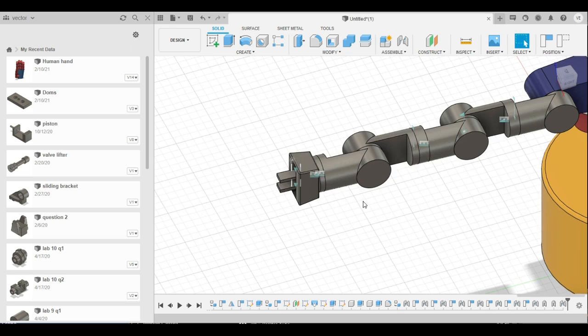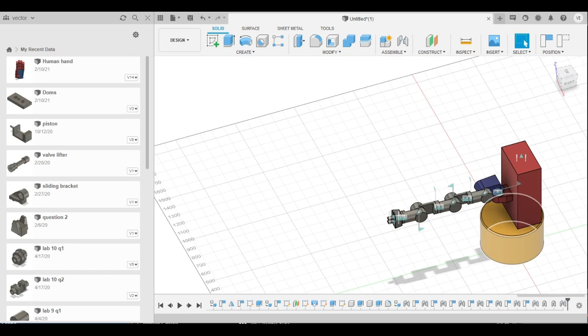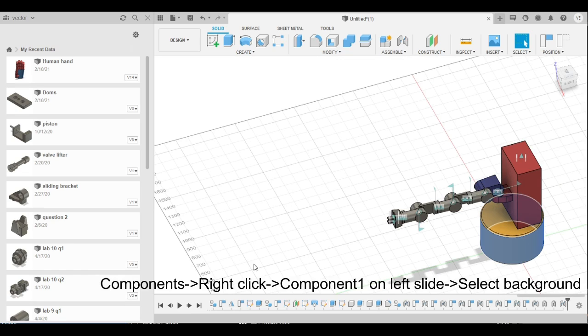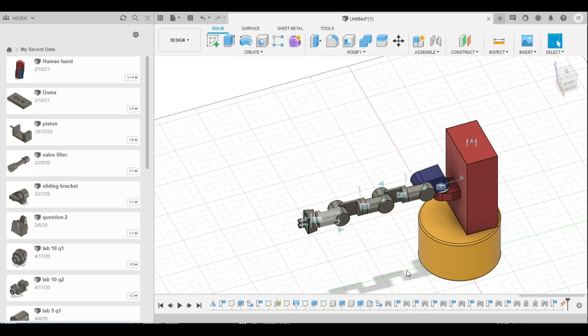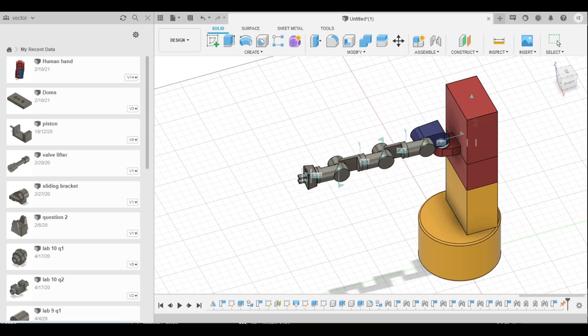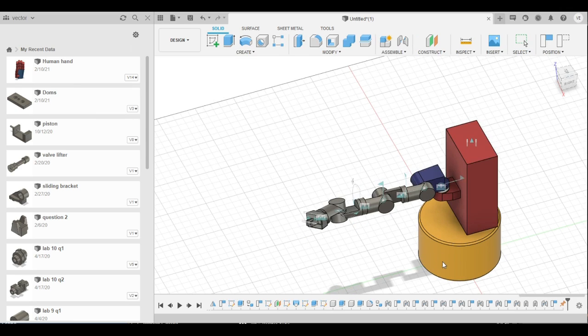As you can see, this one is called the end effector. You can see there are many revolute joints and rigid joints in the middle. So we'll be grounding the base component. Grounding means it stays constant in its place. Once it's grounded, everything moves as it's constrained. You can see I can play with these joints like this. This can move like this. This can move.